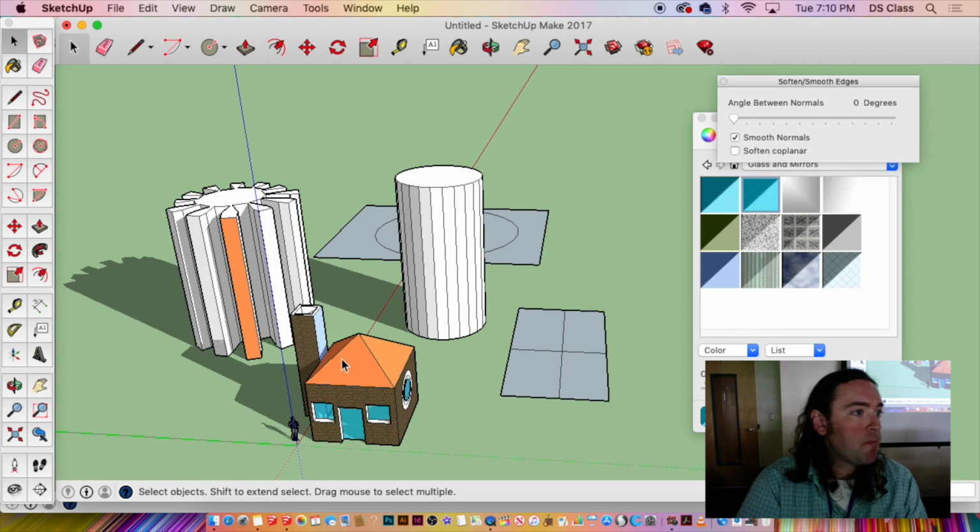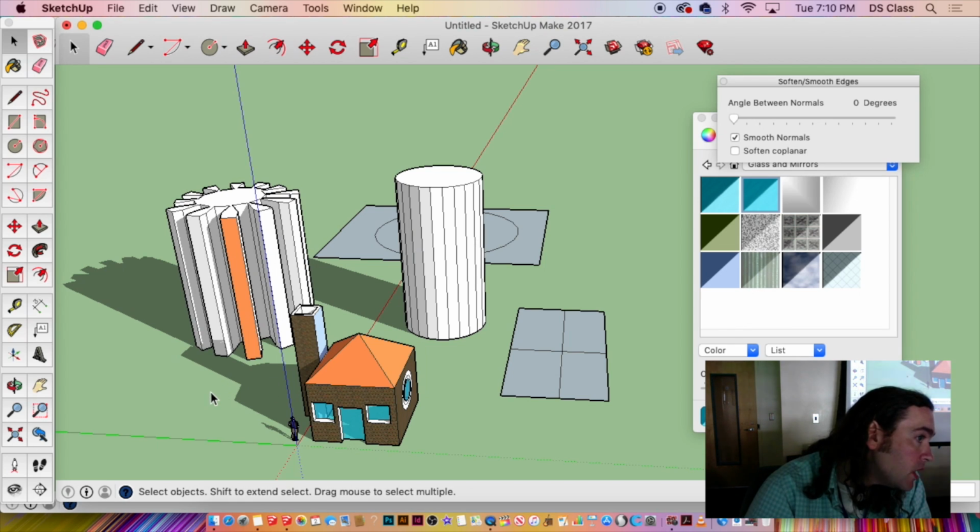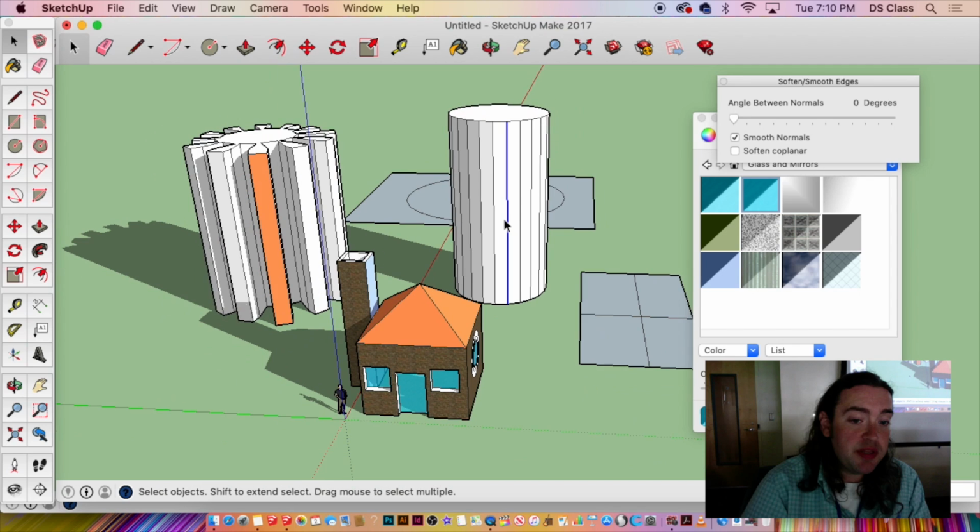So this is the thing. I'm going back to what I showed you before. See that piece inside my circle? That's from the other circle on the other side. How do I remove that? Select it, and then start hitting the delete key. But is it going to delete the circle or just that piece? It depends. If it's grouped, it's going to delete everything you have selected.